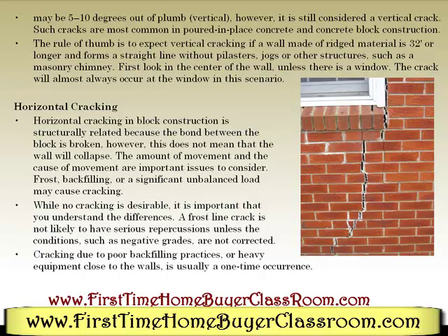Horizontal cracking in block construction is structurally related because the bond between the blocks is broken. However, this does not mean that the wall will collapse. The amount of the movement and the cause of the movement are important issues to consider. Frost, backfilling, or significant unbalanced load may cause cracking. While no cracking is desirable, it is important that you understand the differences.